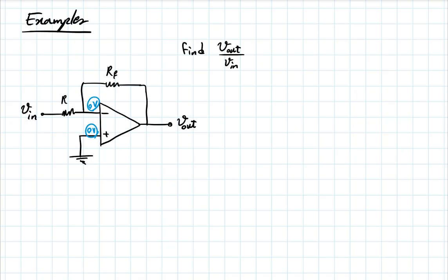What about the currents? How much current is going through this? What is the current going through here? If this is an ideal op-amp, 0 amps. How much current is going through here? Also 0 amps. Infinite input resistance. So it's starting to look like a very boring element, 0, 0, 0, 0. Okay? Well, what else do we have? Let's see. What can I say now?